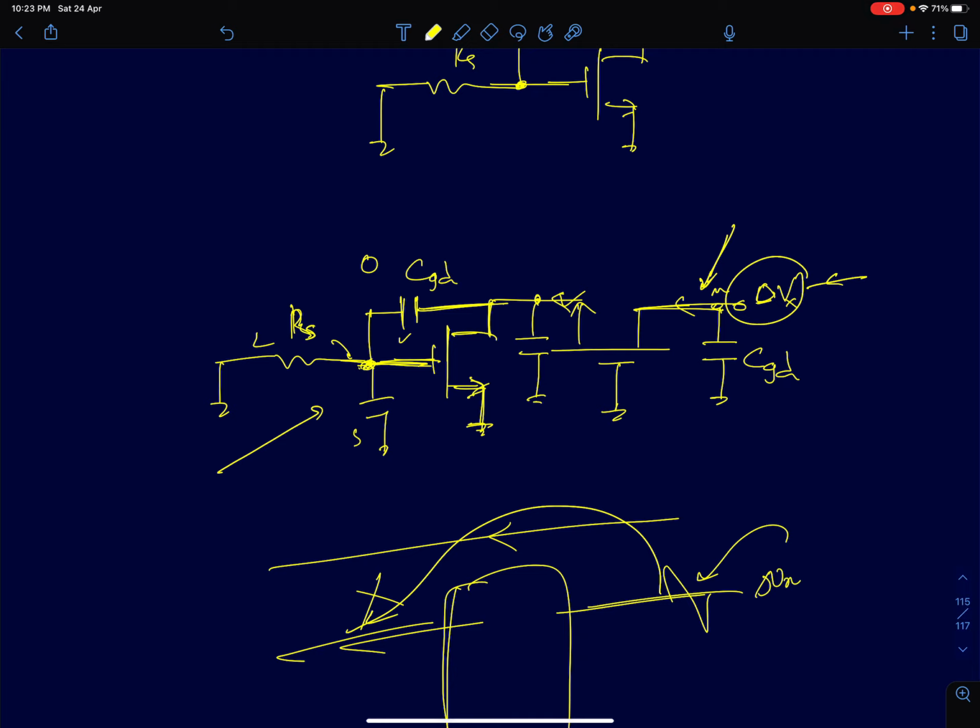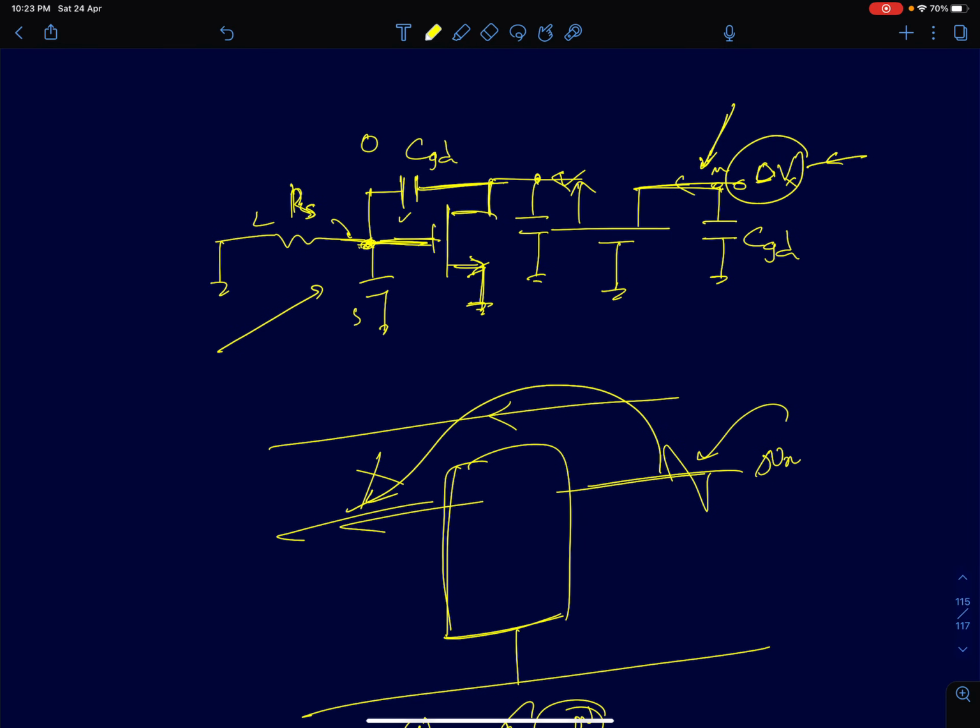So this is what we have discussed about cascode amplifiers. We listed out its advantages. We looked at historically how cascode amplifiers were developed first. We saw the benefits cascode amplifiers offer for resistive loads. If you're driving a resistive load, then definitely you get a huge bandwidth advantage, especially with a large source resistance. If you're driving a pure capacitive load, then you get a much higher DC gain compared to a common source.